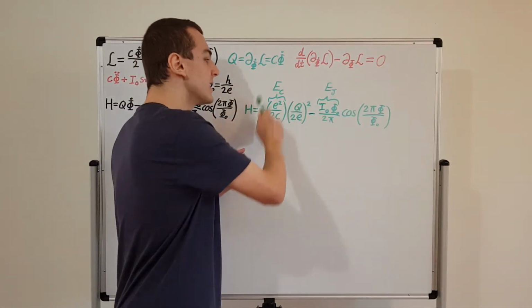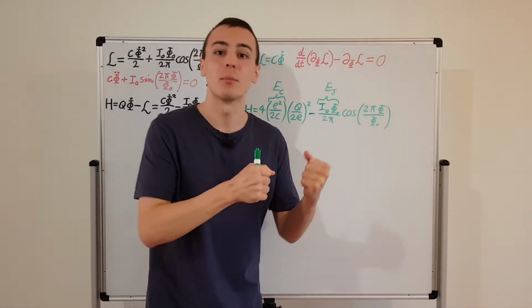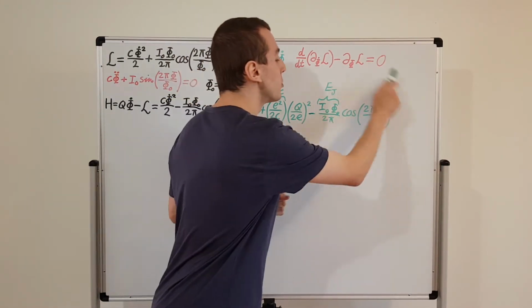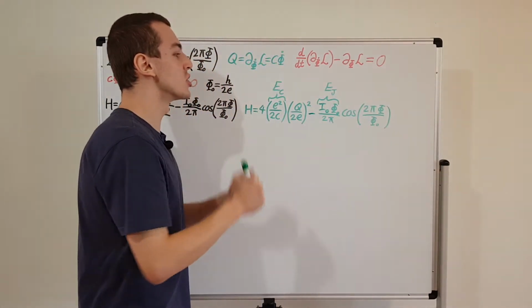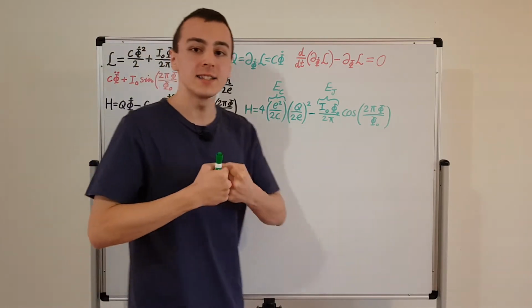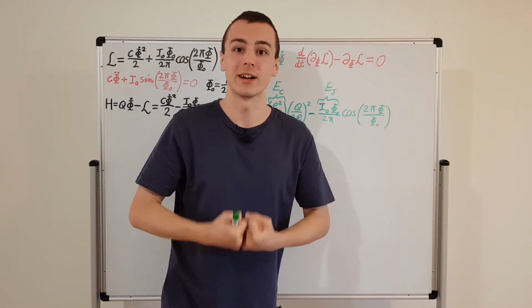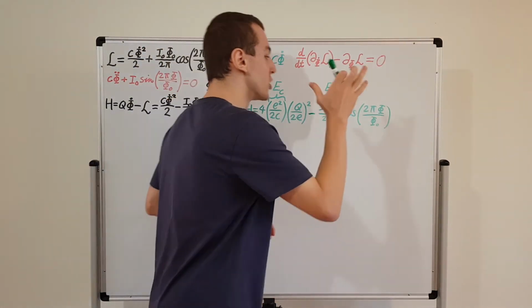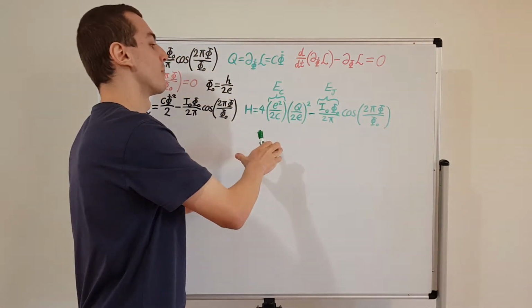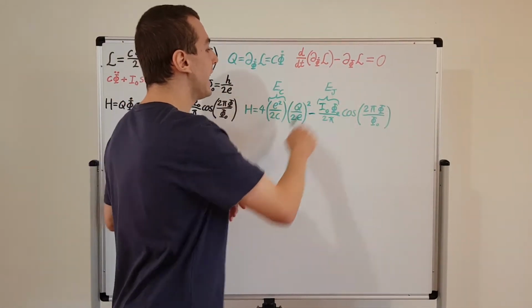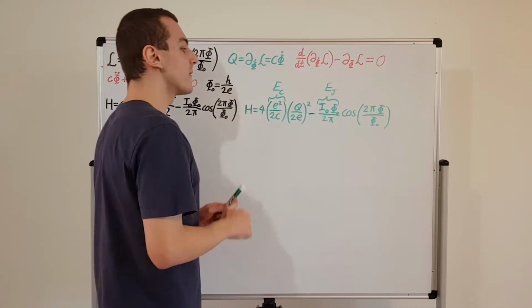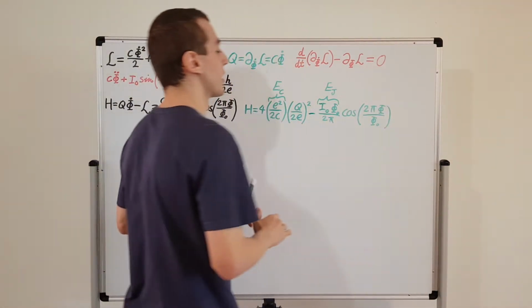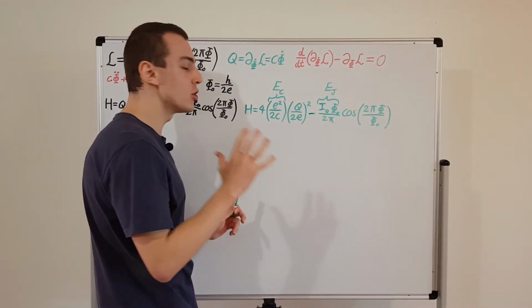So we have this energy over here, which is associated with a capacitor, and this energy, which is associated with a Josephson junction. And that is a very important device in superconducting quantum devices. So we have a Josephson junction and a capacitive term. And that's why we have EC and EJ. I also want to define new operators over here. But first, let me promote these guys to operators.